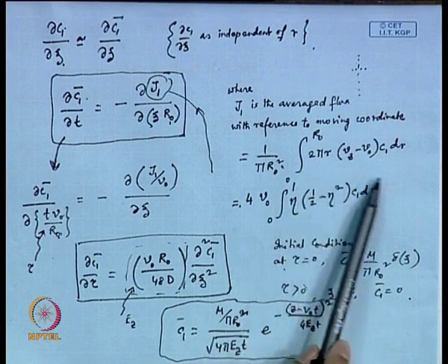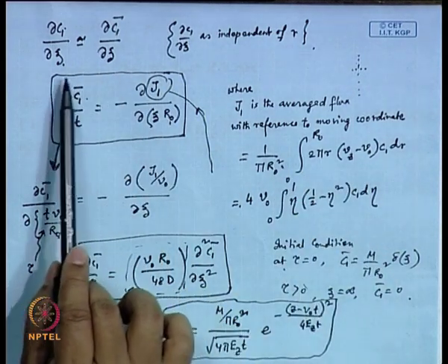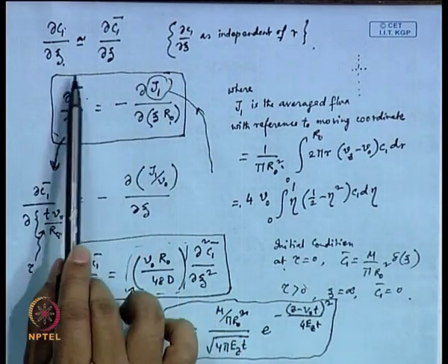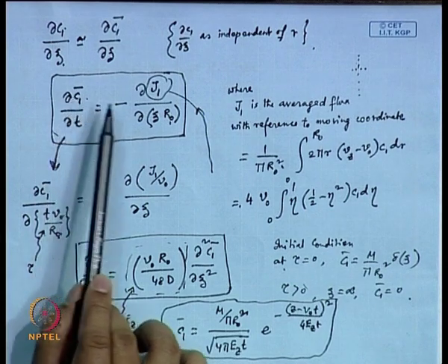You have already compressed that, you have already taken care of that radial part, you are working with the average concentration, and you are trying to find out how the average concentration changes with reference to zeta, mind it, not z, zeta is in moving coordinate system. So, any J1 bar, because of this convective flux, has to be calculated with reference to this moving coordinate system. So, that is how we have written here the J1 bar. Okay, so J1 is the average flux, and that J1 appears here. Now, this is your modified governing equation, with C1 bar and J1.